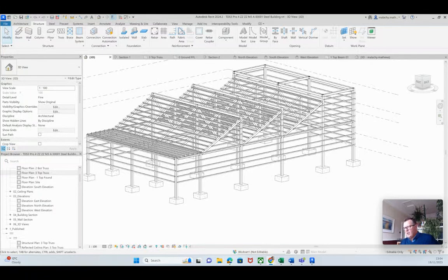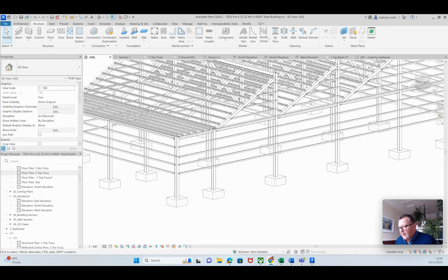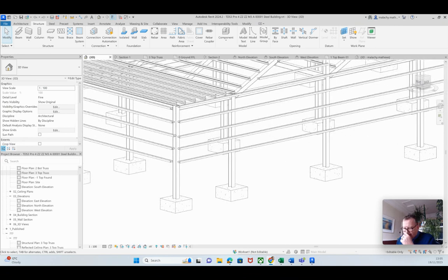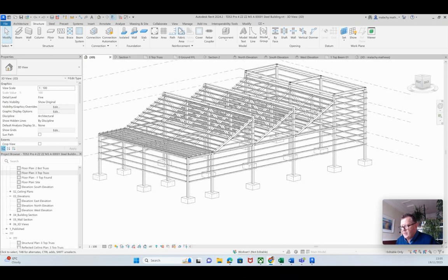Now, students, finishing off this structure here. I want to show you what I've done. I showed you how to create these rails using the reference plane, creating the reference plane using the flat surface of the columns here. That is just repeated on each of the four sides.